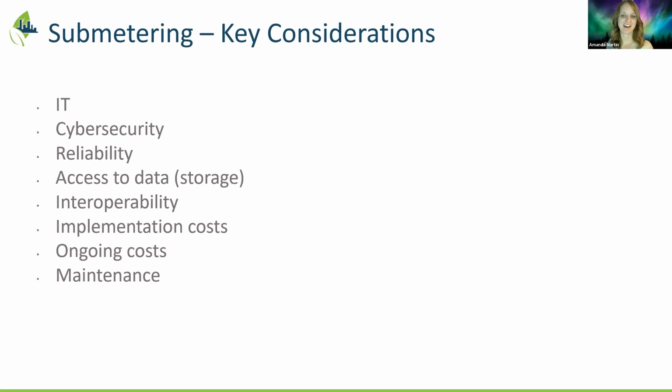Also, personally, maybe the metering companies don't want to hear this, but I always try to prioritize as many free meters as possible through the utility companies. They install them, own, operate, and maintain. So it's easier from our end. We just have to run a cable for them, and then we access the data through their software.